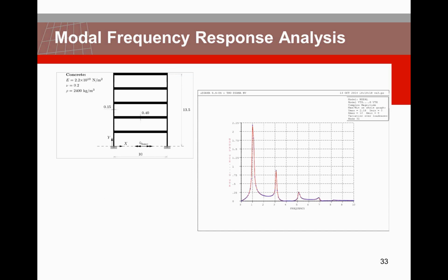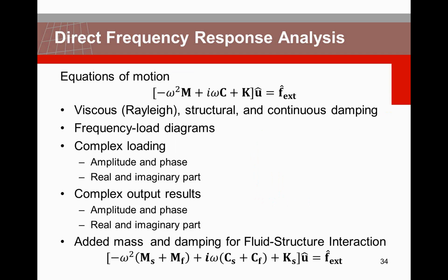If you want to do that, we will come to the direct frequency response analysis, because what you see here, there is your real damping matrix. So if you have structural dampers or continuous damping involved, and you want to calculate in the frequency domain, you need to go to a direct frequency response analysis. Also here the same story about the loading and the output.